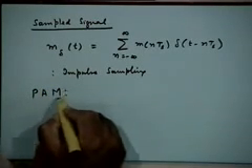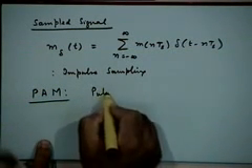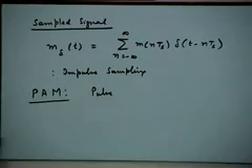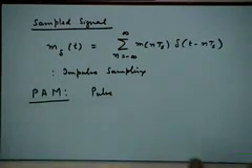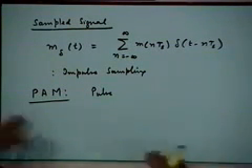The first kind of modulation that we discuss is called pulse amplitude modulation. As you see, the basic concepts are the same. You have a pulse train which is your carrier. Instead of a sinusoidal signal of some frequency, you have a pulse train as the carrier. You want to embed the information that you want to convey on this carrier, right. Again, how can you do that? You can modify some parameter of the carrier in proportion to the information that you want to embed, right.